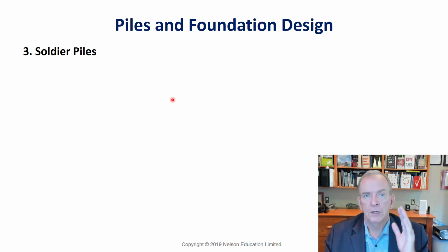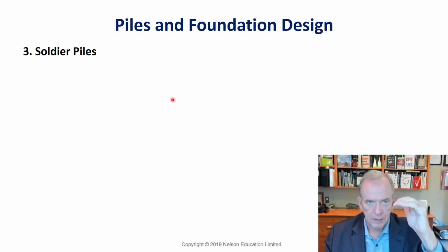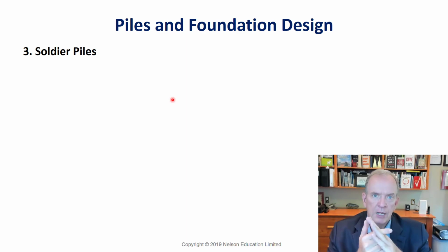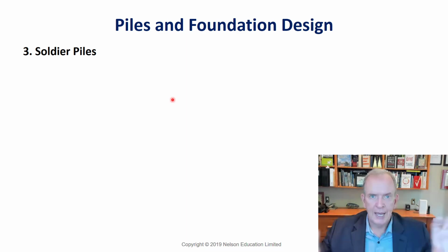Well, soldier piles are driven into the ground, and instead of them supporting basically weight, compressive loads on top of it, it's supporting lateral loads against it. And if they're deep enough, they'll also have tiebacks that are drilled into the side of the soil surface to prevent it from pushing inward. Typically you have steel supports, and then you have wood lagging that goes in between to support the soil. It's actually acting like a retaining wall, if you will.